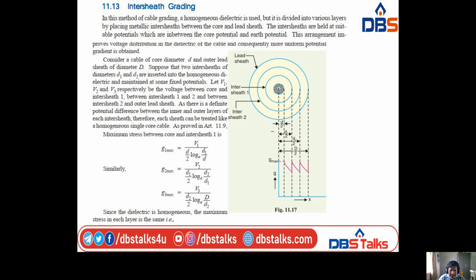Now look at the diagram. Let us consider a cable of core diameter small d and outer lead sheath diameter capital D. Suppose two inter-sheaths of diameters D1 and small d2 are inserted into the homogeneous dielectric medium, and each is maintained at a fixed potential. Let V1, V2 and V3 respectively be the voltage between core and inter-sheath 1, between inter-sheath 1 and inter-sheath 2, and between inter-sheath 2 and lead sheath.